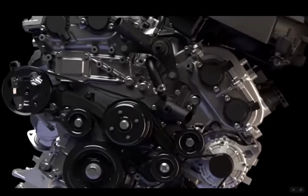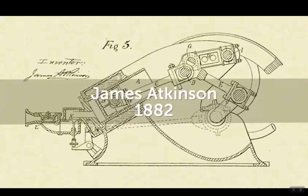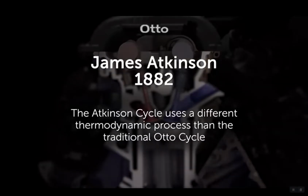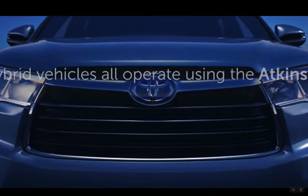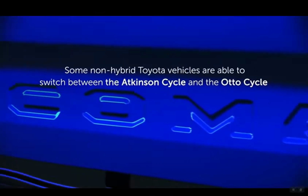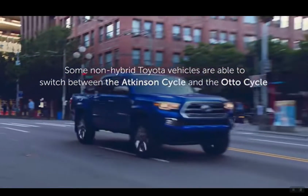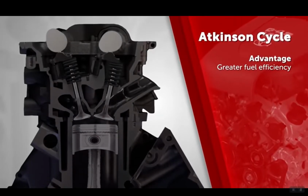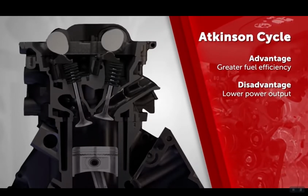The Atkinson cycle is a method of internal combustion first proposed by English engineer James Atkinson in 1882. The Atkinson cycle uses a different thermodynamic process than the traditional Otto cycle common to most gasoline engines. Toyota hybrid vehicles all operate using the Atkinson cycle, and some non-hybrid Toyota vehicles are able to switch between the Atkinson and Otto cycle as needed. The Atkinson cycle is more fuel efficient than the Otto cycle, but this efficiency comes at the expense of power output, which is why it has not been widely adopted.